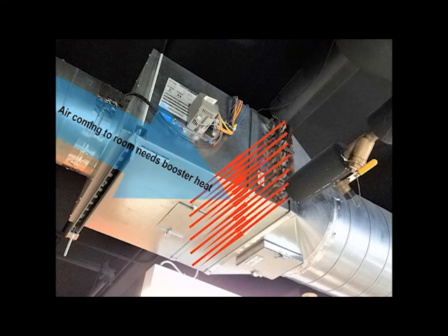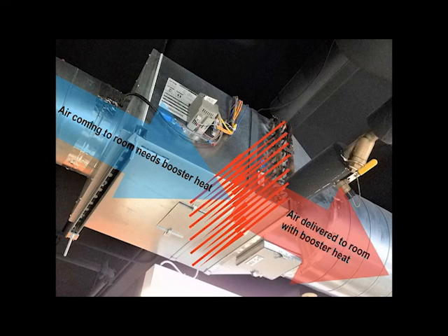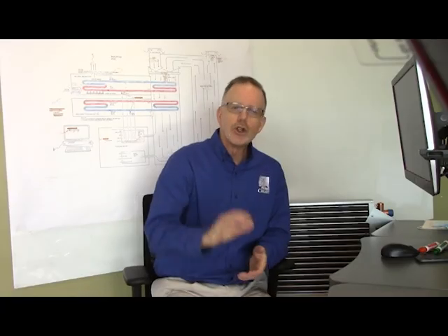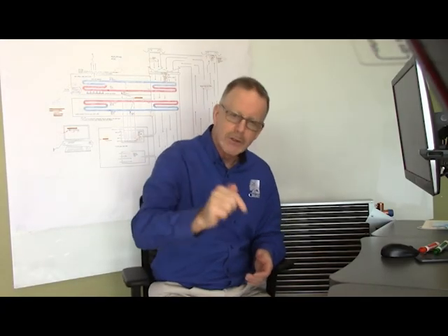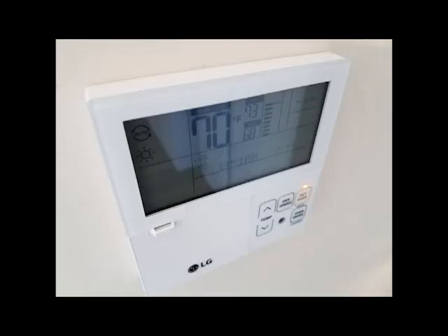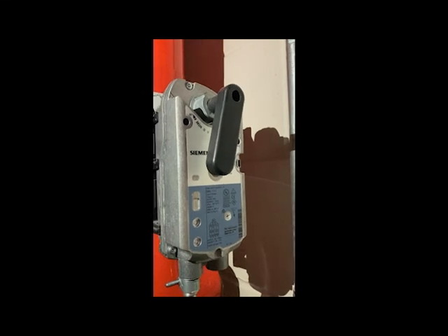Air from the building or bulk air supply that isn't quite warm enough is blown or forced through the booster coil in the VAV box. The booster coil provides additional heat to the air moving through it. That extra heated air then enters the room or building space that needed the extra heat. You could probably figure out the rest of the story from here. The sensor begins to sense the boosted temperature. As the higher temperatures approach the programmed set point, the controller activates the actuator again. This time, the actuator physically begins to close the valve and may eventually fully close it.